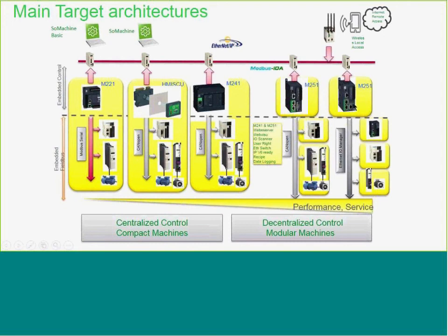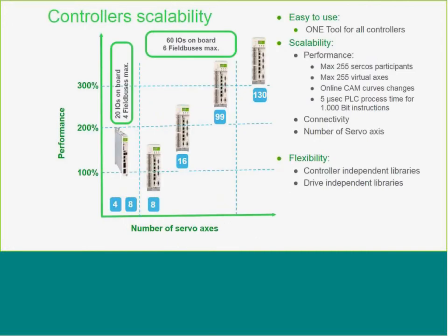And then we get into the higher end PLC solution with our M251 and remote I/O, and we can do CANopen. It is a native fieldbus on all Schneider Electric products, the most economical fieldbus. But as we get more precise and more high-speed data exchange, we have an Ethernet protocol also. All of these are available in different fieldbus connectivities to communicate up and downstream. And so more centralized and decentralized control systems can be expanded upon also.